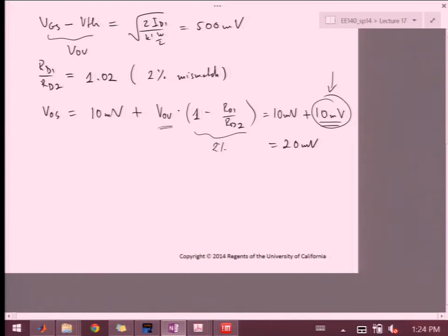So here you see there is a trade-off between accuracy and speed. As we said, the fT of a MOS is dependent on the overdrive voltage, right? So if we wanted a faster transistor, we could affect it by the overdrive.